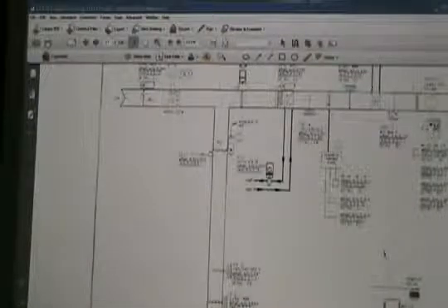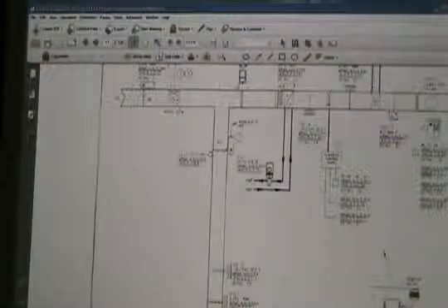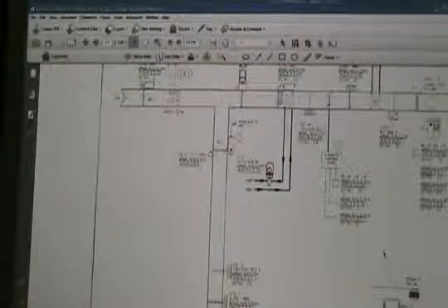Engineers forgot something. It should be just like you had the damper positions going up and a way to go backwards. You should have an override here. Probably we'll go ahead and do it. We can't maintain 55. We're going to drop that back down to 4,900 and let the building be negative, or send an alarm, so someone's got to address the problem.